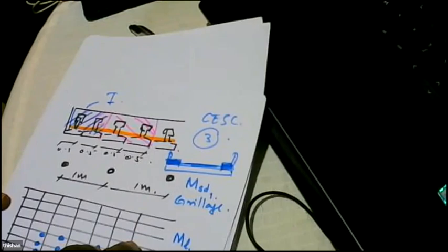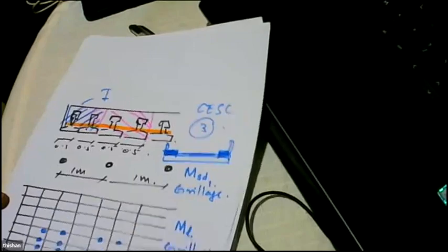So basically they wanted to make sure all the beams are held together. The beam had some slots, and through the slot you put a 25 millimeter bar and connect all the beams together. And they found the behavior is very satisfactory, a very stiff structure, and ideal.